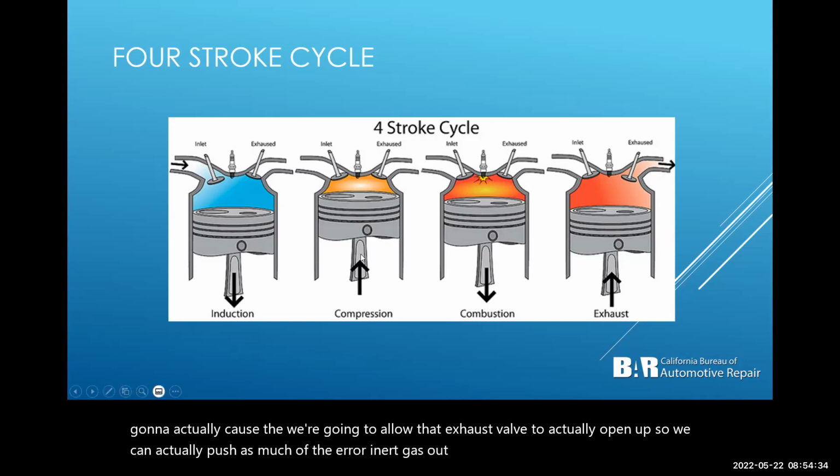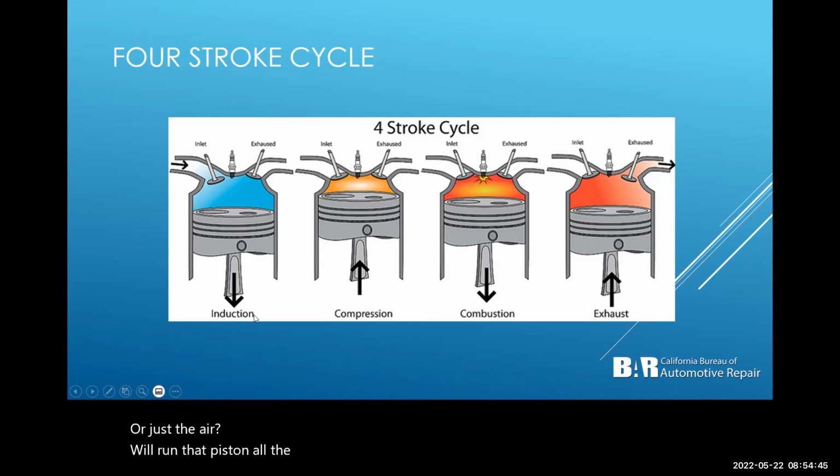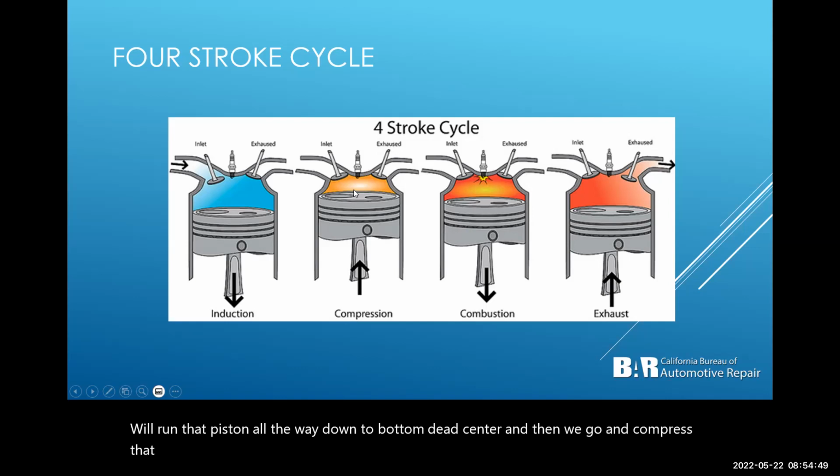And then we'll start the whole process over again. So again, we take an air fuel charge in, or just the air. We'll run that piston all the way down to bottom dead center. And then we go and compress that air. So this is the compression stroke.